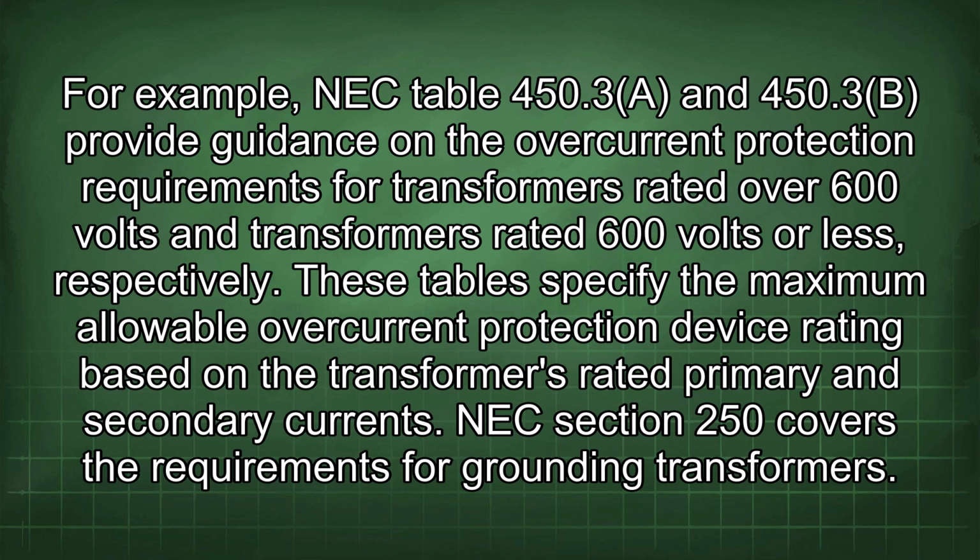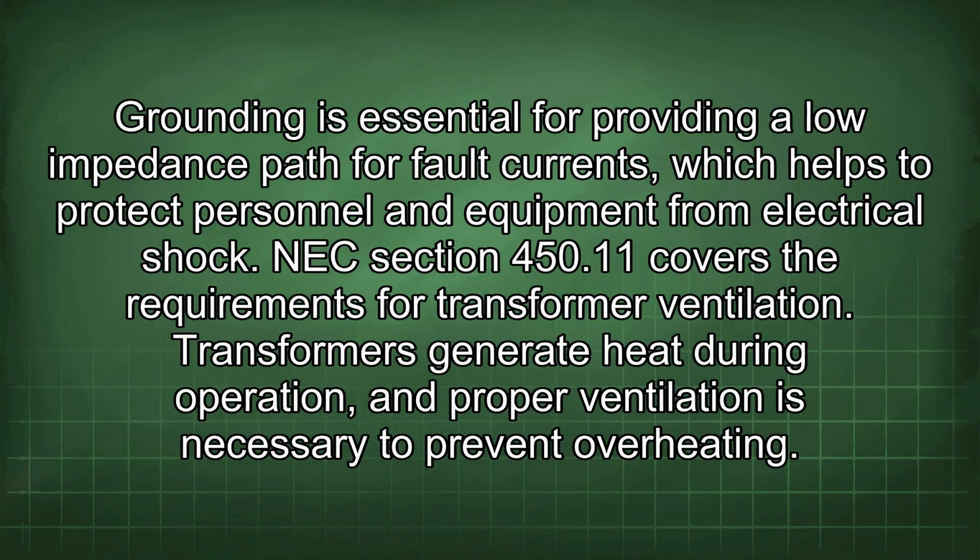NEC Section 250 covers the requirements for grounding transformers. Grounding is essential for providing a low impedance path for fault currents, which helps to protect personnel and equipment from electrical shock. NEC Section 450.11 covers the requirements for transformer ventilation.